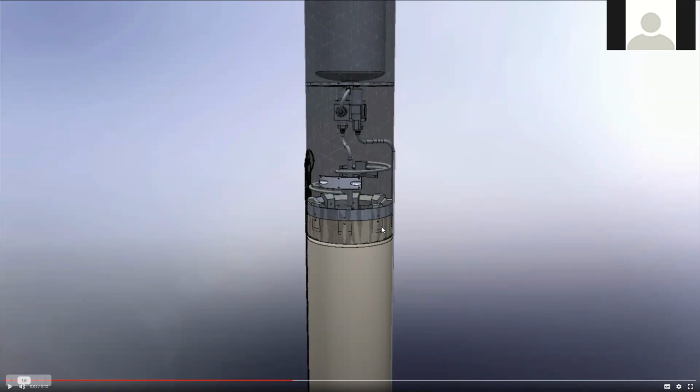But developing a pump system that is that small and that light is extremely complex, especially when you're dealing with something that's cryogenic, like liquid oxygen. It's possible you could do it for, say, the kerosene that we use. That would be much simpler. But a cryogenic pump that can sustain the flow rates that we need and be lighter than an equivalent high pressure helium tank is quite difficult.